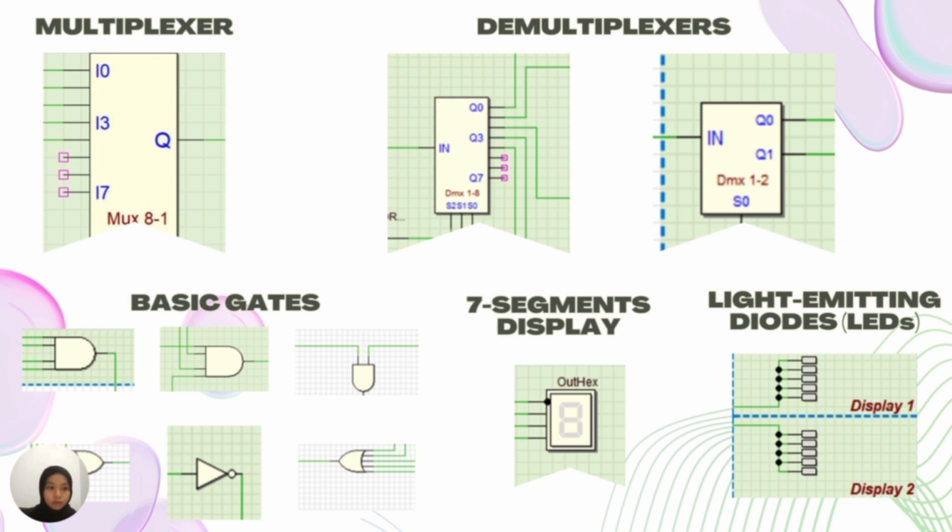The circuit uses two OR gates, three AND gates, and one NOT gate. The OR gates detect active computers in Lab 1 and Lab 2, sending the result to the first AND gate. The first AND gate checks activity in both labs for the clock enabler, and then the second AND gate validates password inputs, while the third AND gate generates a clock signal when all inputs are high, enabling the flip-flop. The NOT gate inverts the comparator output to control the subsystem.